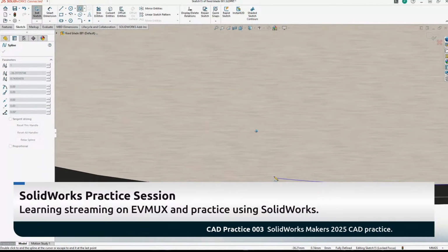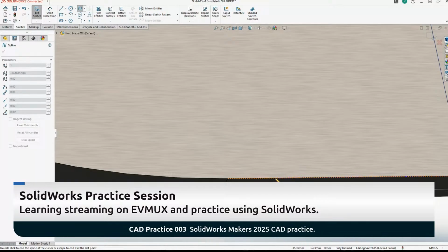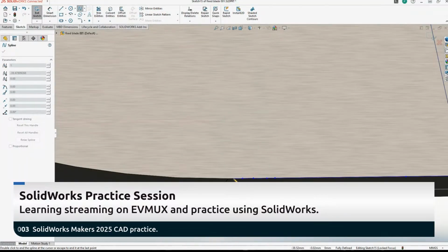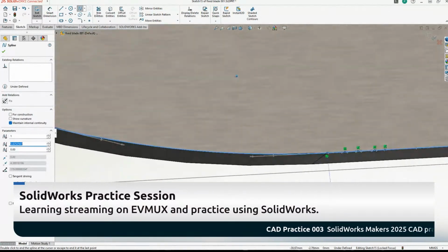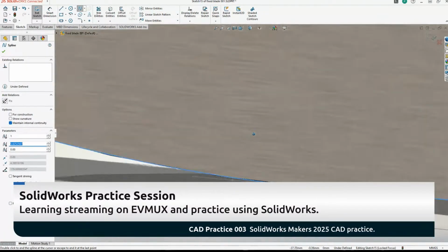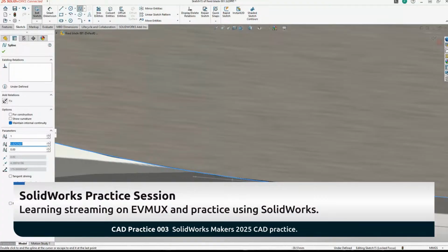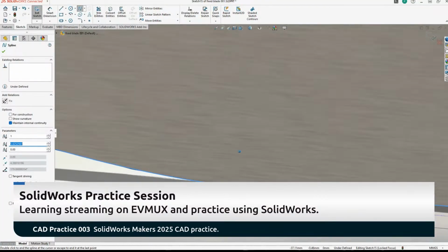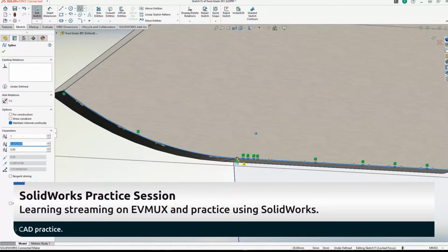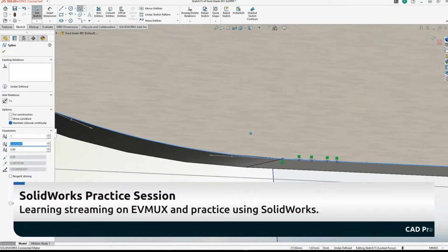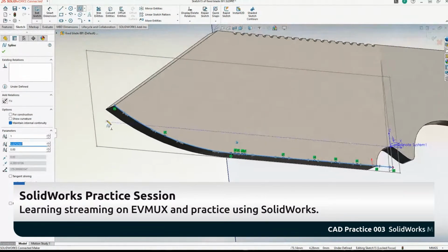And then up here where I want to start curving up, I'll just put several really close together so that when I go up here and then to here, it's barely noticeable if at all. So when I use the cutting tool, it'll get rid of any slight imperfection just between these two points that might have occurred the way I created this spline.